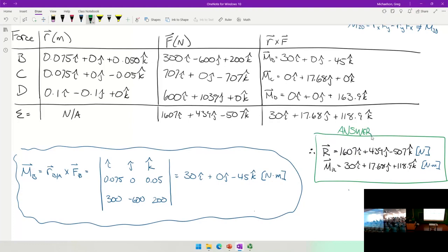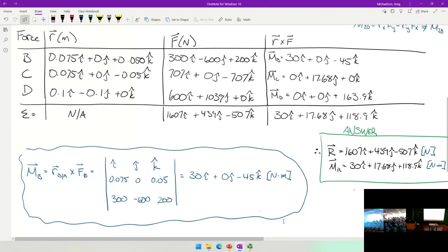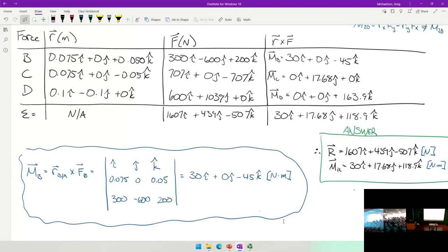See, this was a really, really short problem, and if anybody snuck a peek at the slides before the lecture, it probably looked incredibly nasty. Really the point I want to make is that if you've got position vectors and force vectors, then the process of collapsing them into a single equivalent force couple system of a single force and a single moment really should be very easy. Okay, and I hope it is.